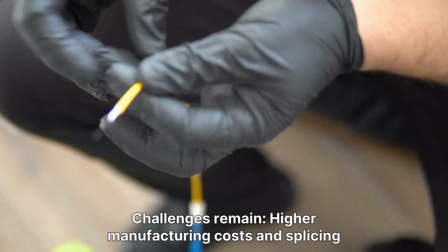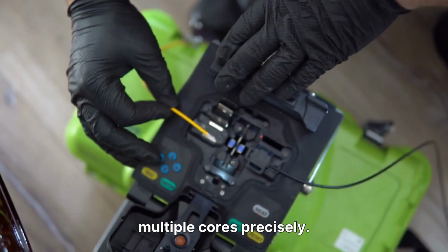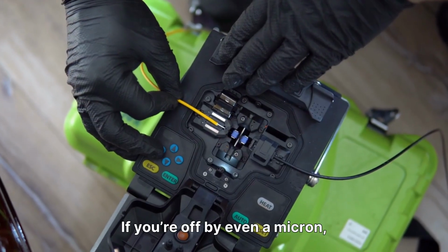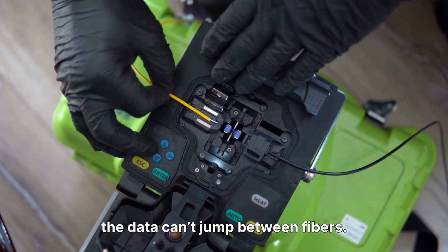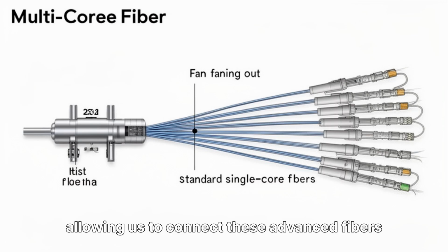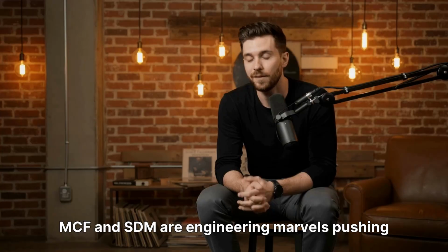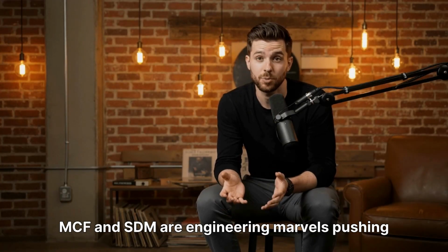Challenges remain: higher manufacturing costs and splicing multiple cores precisely. If you're off by even a micron, the data can't jump between fibers. But solutions like fan-in, fan-out devices are emerging, allowing us to connect these advanced fibers to our current network hardware seamlessly. MCF and SDM are engineering marvels pushing boundaries.